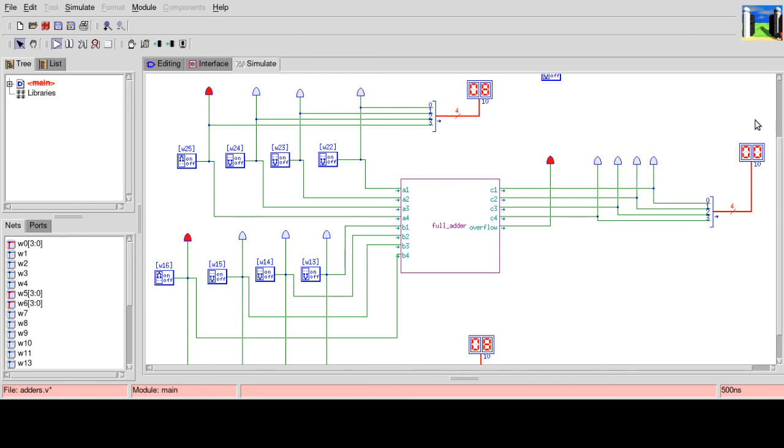Okay, I purposely set up my LED here to just be off of the 4 bits that are part of the answer that the computer can retain, and throwing away the overflow bit. Okay, this is what's known as a 4-bit computer. Most computers are actually 64 bits, although there are some older 32 bits. That's going to become important later, which is why I wanted to show you that there is this thing called an overflow. But you know what? Since we're here, let's just play with it a little bit more.